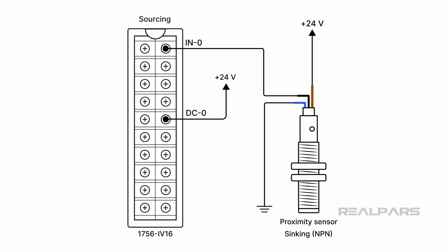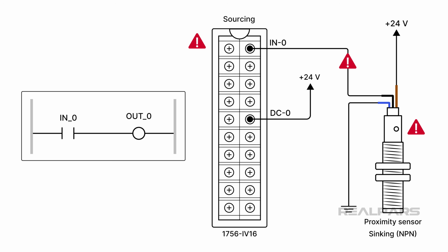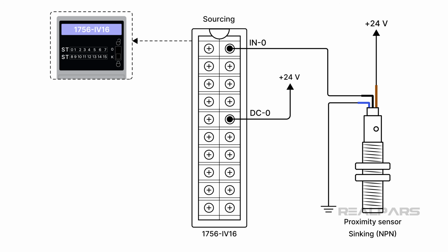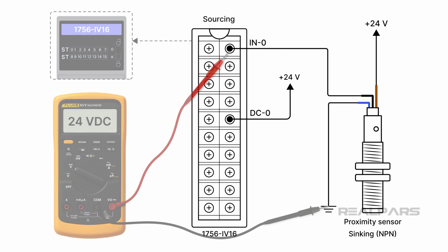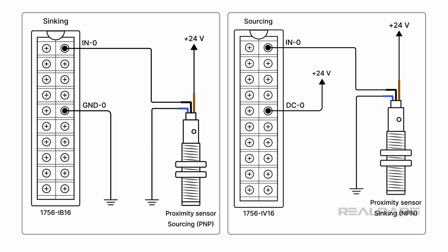As we said earlier, the majority of PLC faults originate from field devices, I/O wiring, and occasionally the module. The PLC software itself is rarely at fault. LED indicators are undoubtedly helpful, but measuring the actual input voltage is the only reliable way to confirm what's happening. Understanding sinking and sourcing inputs and the expected voltage ranges on modules will take you a long way on your troubleshooting journey.